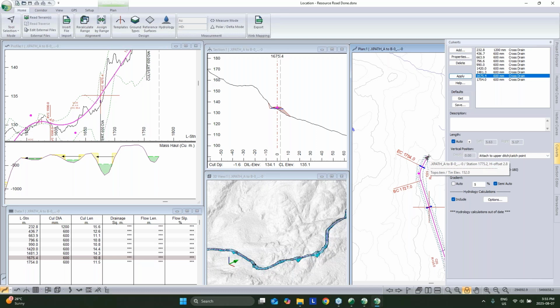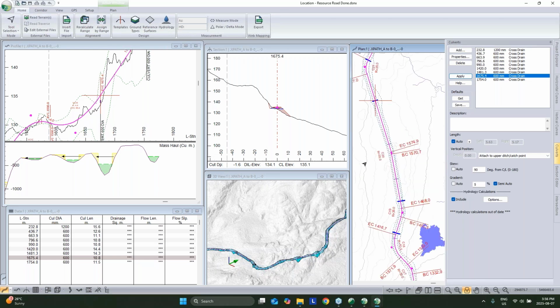They're going to be intercepting flow and redirecting things certain ways. And if you've got a road with switchbacks, well, those ditches are redirecting flow away from the road below, or concentrating it where you've got your cross drains. So it is nice to account for as much as you can with this stuff.